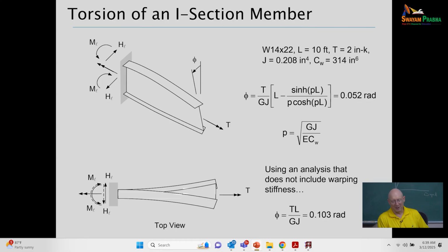So this is a very simplistic illustration using a first order analysis. Warping rigidity is very important when it comes to twisting in these types of structures. That's one of the highlights of Consteel: everything in Consteel is based on including that warping.